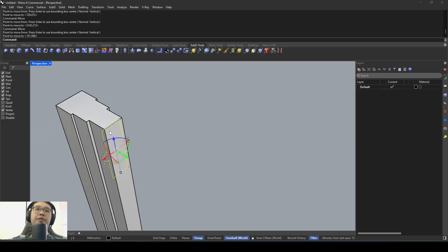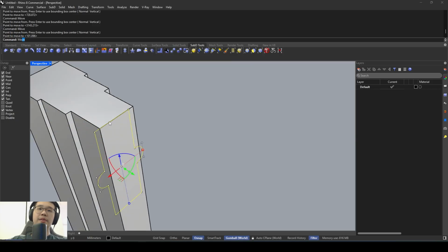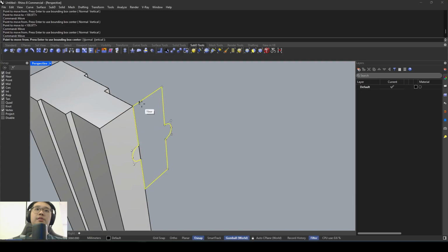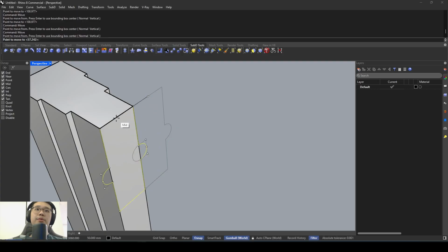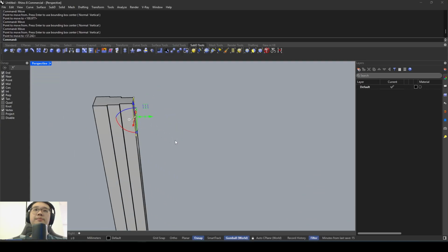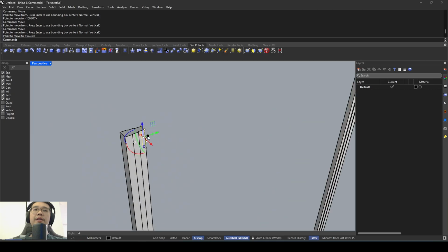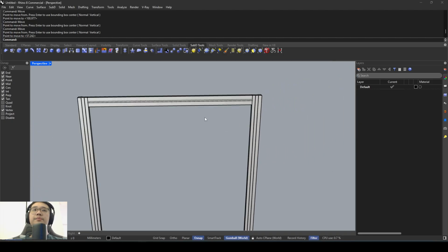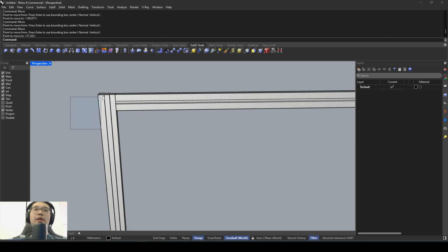And do notice that it's not currently centered at the moment. I'll just move this to here. So you can move from center to center, like this. So we can now extrude this forward by typing in 2600. And that's it. And then I'll highlight this curve here by highlighting left to right.